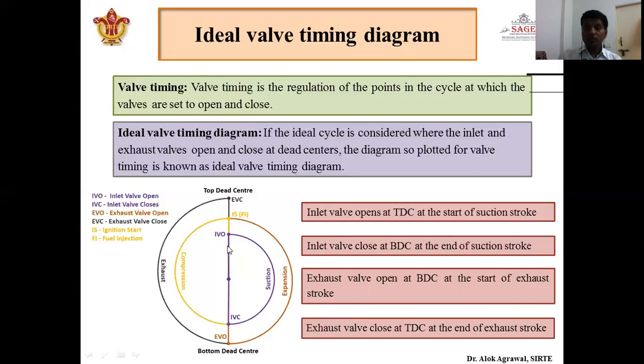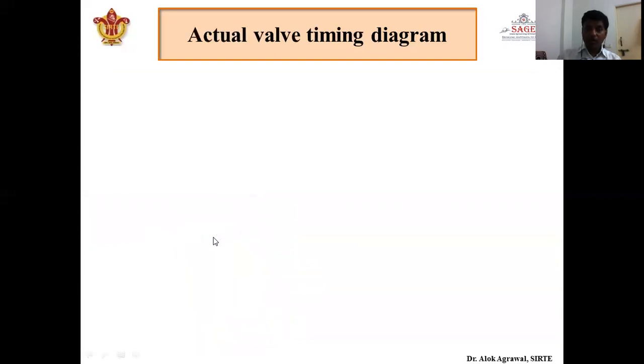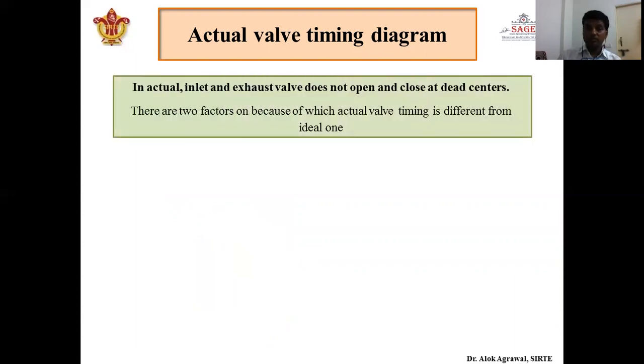But it is not the actual case, because there are other factors because of which the actual valve timing diagram cannot be the same as the ideal valve timing diagram. In actual, the inlet and exhaust valves do not open and close at dead center.